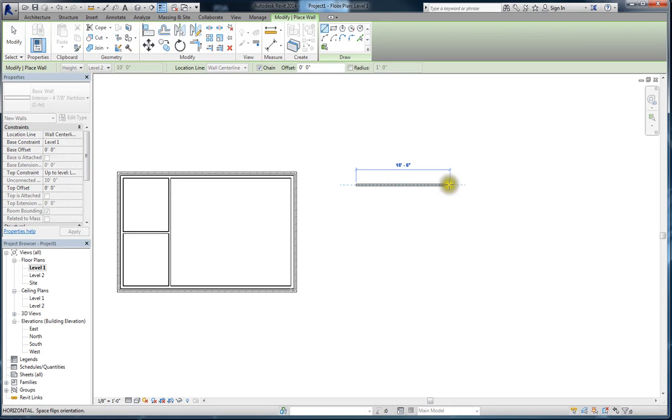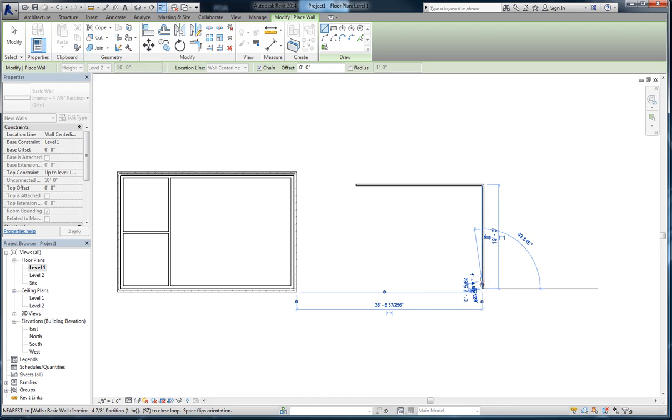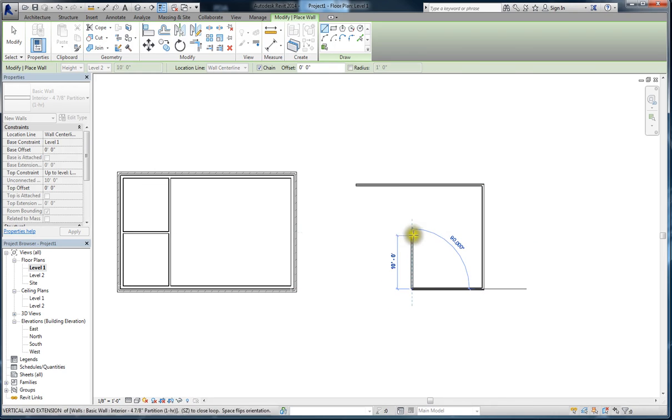You click on a start point, and on the keyboard you type the distance that you want. So you just move the mouse to whatever direction you want, and let's say I want here 25 feet, so I just press 25, enter, and it does 25 feet. And then I continue, and I can just type the distance. I want 19 space 6 equals 19 foot 6 inches. Okay, so that's another way to do it. 14, enter. Let's say somewhere about 10, enter, and then continue.